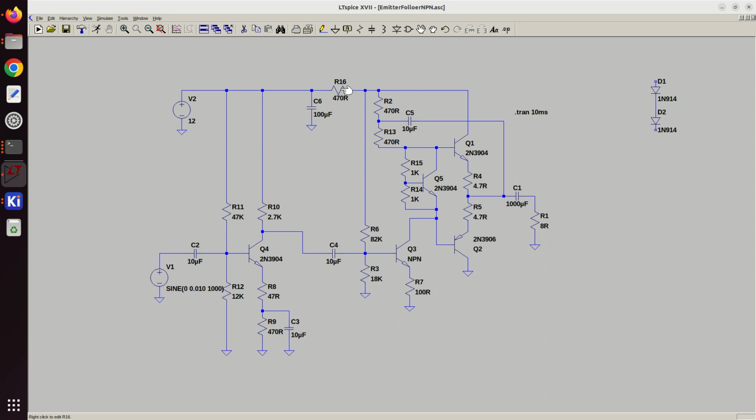So I said this is basically the voltage, it shouldn't come in this way then. So let's disconnect that guy. We don't want a 470 ohm drop on the high power, but it's fine here when the currents are really low. So let's move this guy to the opposite side.